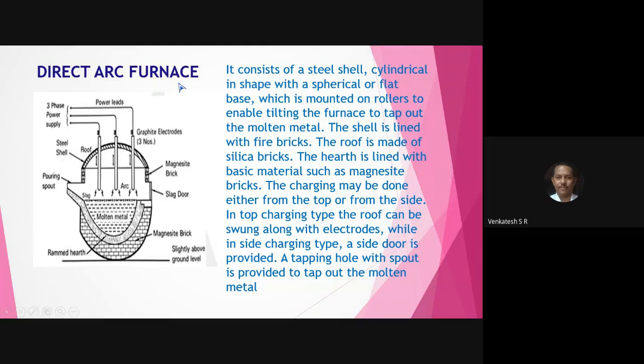Write down all of you the title direct arc furnace and write down the rough diagram of direct arc furnace. In the bottom, intentionally they have made a curved surface in order to turn the entire furnace 180 degrees or 210 degrees in order to pour the liquid metal into the ladle.